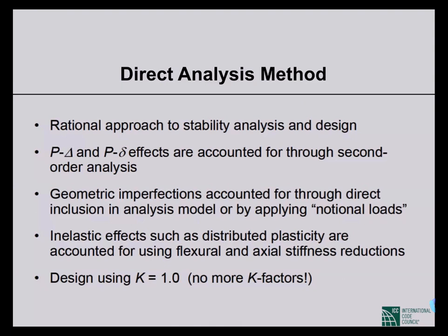So those were some tips about connections. The tables that are provided in the code, how to consult those tables, I have just given those tips. So different types of welds and welding processes, based on them you can determine the throat size, and then you calculate the capacity. And for bolts, depending on the different types of bolt holes and different types of joints, slip critical or bearing type, how to calculate the capacities. So these were some tips for you.